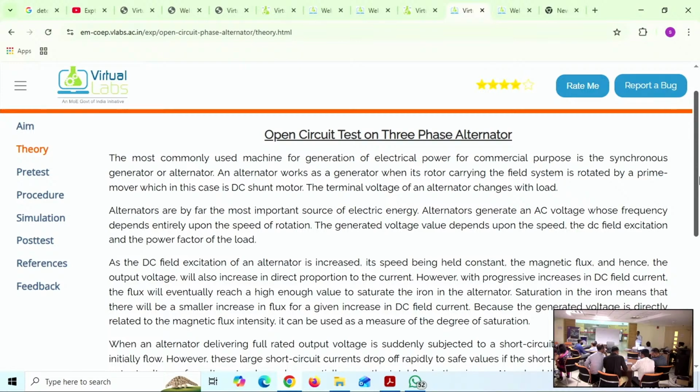Because if you connect the voltmeter, it may draw some current, so the net line current may change. Okay, in that case, when you are connecting the ammeter, the ammeter may have some drop, then the remaining drop will be given to the other circuit, so the voltmeter reads a lesser voltage. Correct. The solution is, both are valid theoretically and practically, depending on the accuracy level.